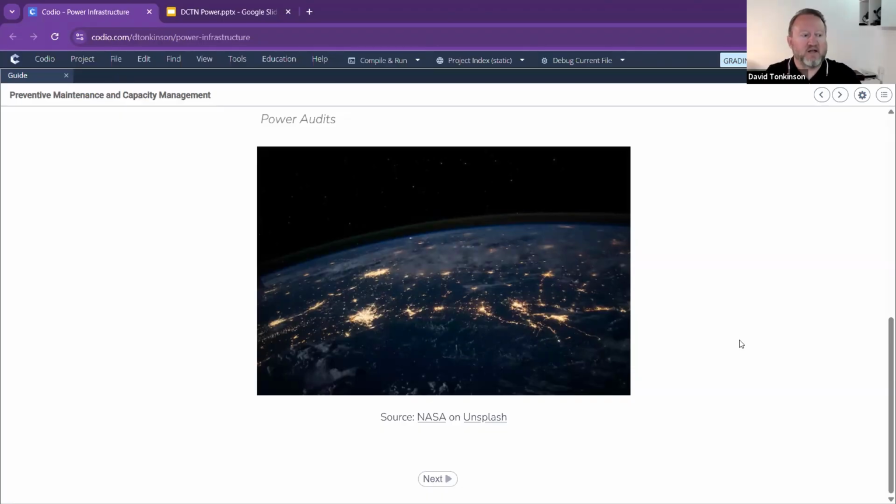This is fantastic. So you can have some circuit balancers that basically measure the output from each circuit, and that will give you some nice, pretty graphs, essentially. And that will tell you where your power is being drawn to. And that's what you basically use when you do those audits. And normally, if you have a data center that is constantly changing in terms of your racking and re-racking items and moving them around, you normally reckon you do a power audit once a month. If you have a system that's fairly stable and nothing new is going in and things are running fairly statically, then you can stretch it out and do it once every 6 months. But that's the general idea.